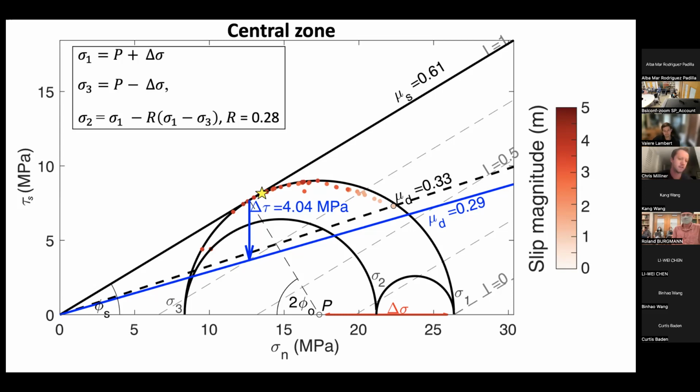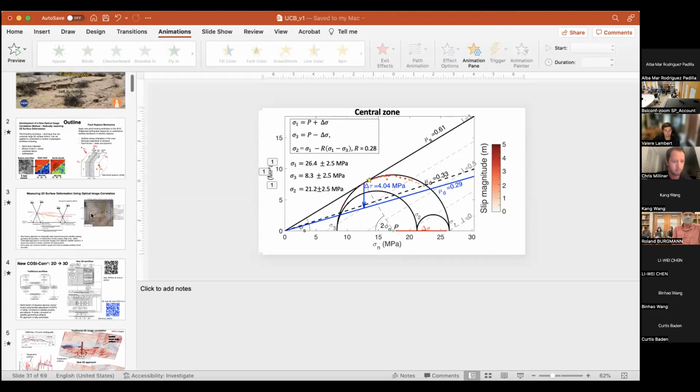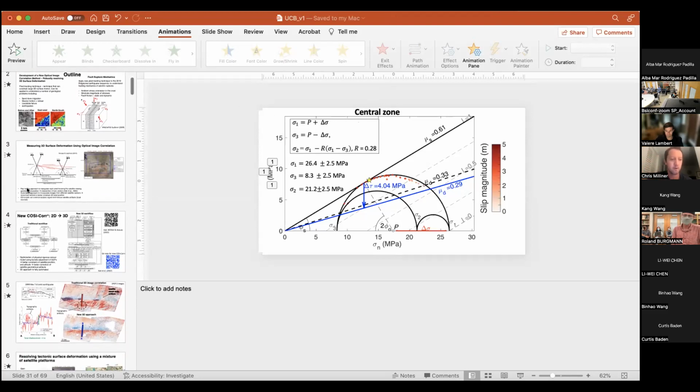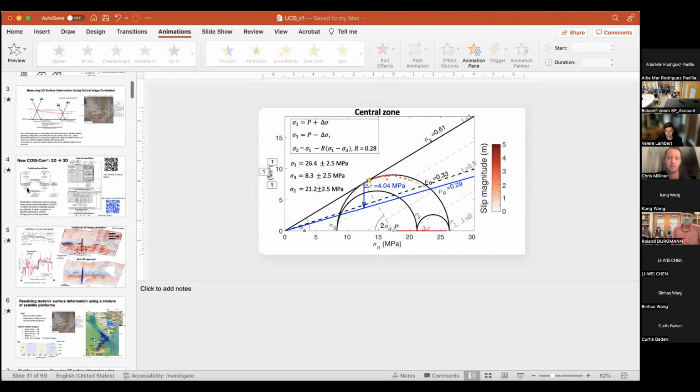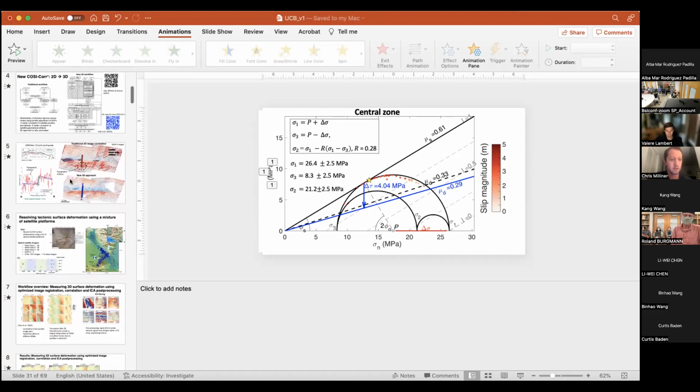I think one thing to consider though is it's two parts to that question. The first part is what's the minimum amount of surface motion you can detect with these images to be able to estimate the slip vectors? And so typically a rule of thumb is that you can resolve about 1/10 of a pixel. So if your images are 10 meters like Sentinel-2, you can resolve a meter displacement. So that's kind of one issue. So like magnitude 6 events, that's going to be quite difficult with optical data. You might be able to use InSAR for that because the phase gradients might not be too high in the near field.